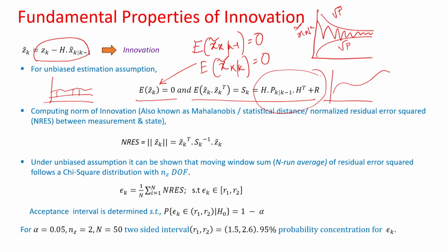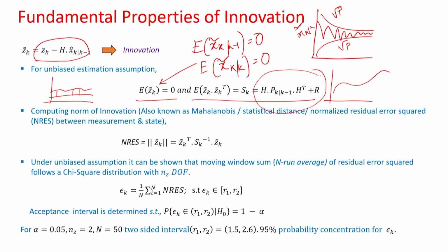Suppose you are operating in a navigation environment and you are given some gyro data and you want to fit some state you want to estimate, and your gyro has a bias. Okay. If you do not correct that bias using a secondary sensor or something, you get a biased estimate of your state. The same thing applies here too. So, that is very important, you need to check that your measurement is bias free, number 1. So, this will give you one correction.